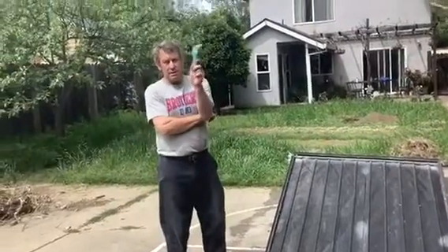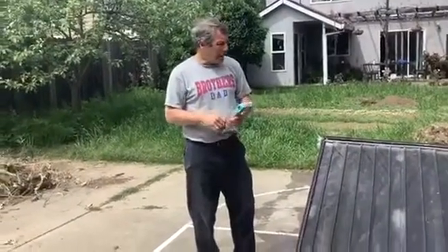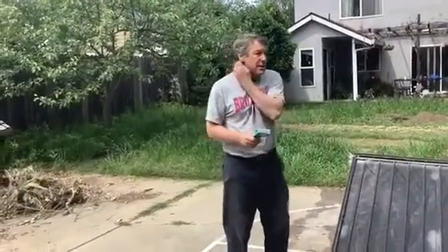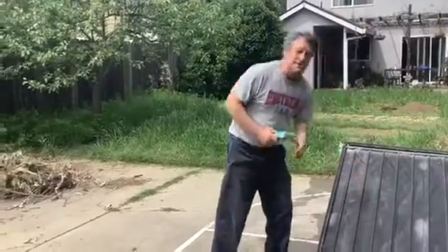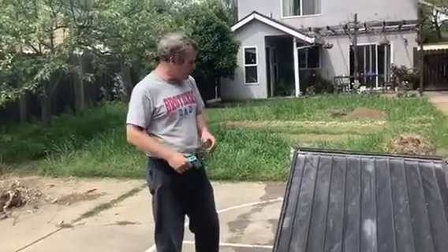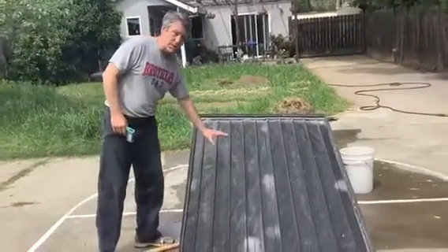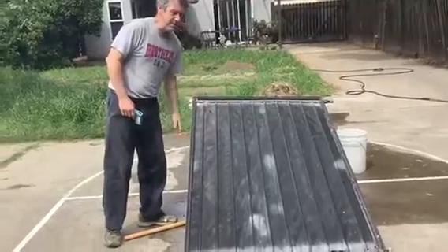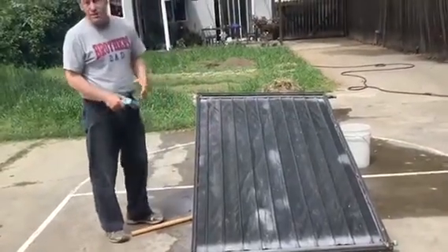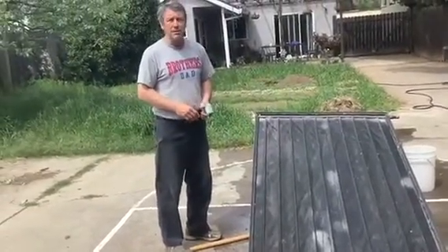This measurement device takes in a certain amount of radiation and has an assumed emissivity. And as a consequence, there's low radiation coming off this, and then when it uses this assumed emissivity to calculate the temperature, it gets a really low temperature. So once again, this is a really nice surface, high absorptivity, low emissivity, and let's just get it going and see how it actually works.